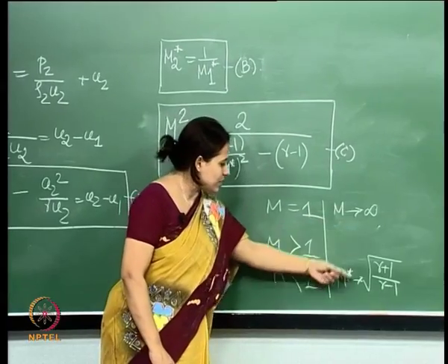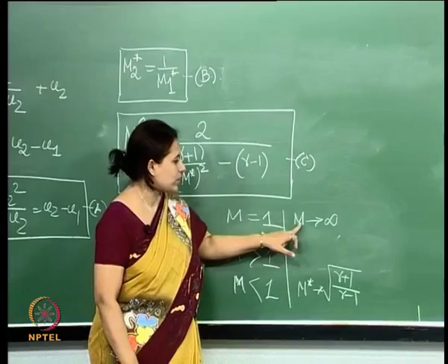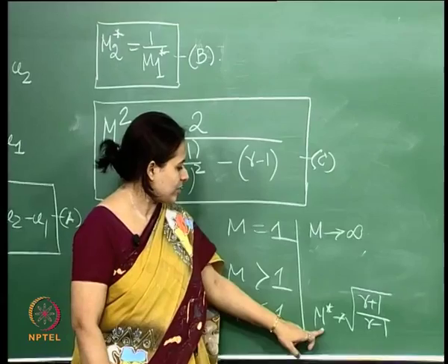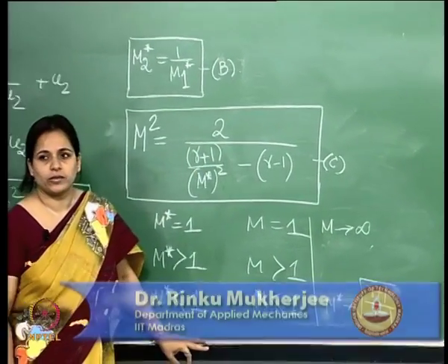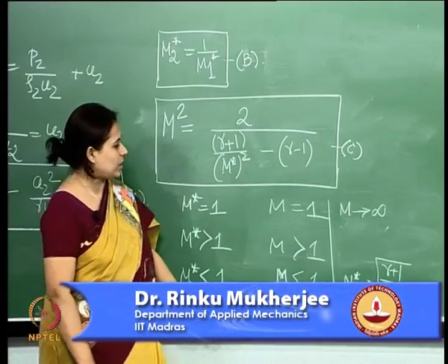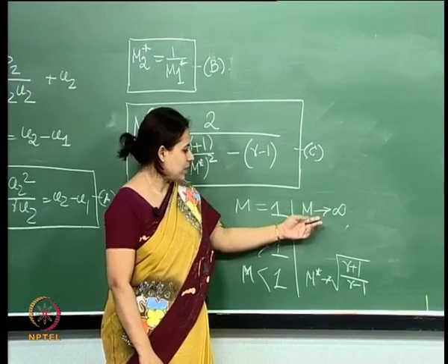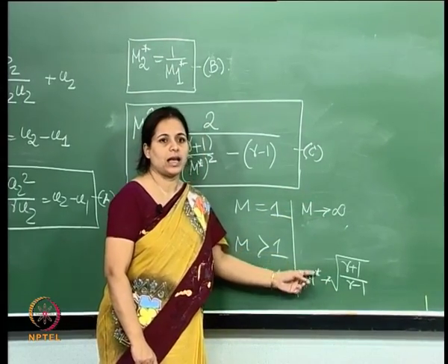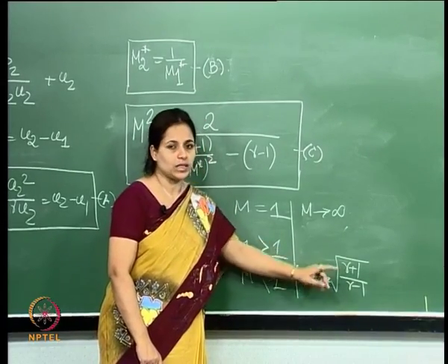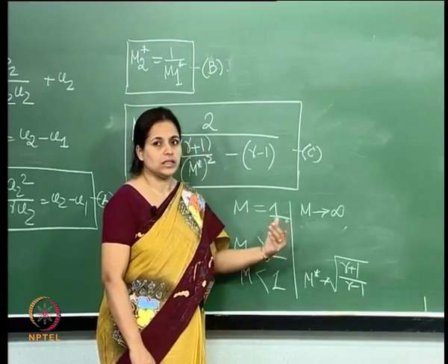Okay. So, what is this exactly telling us? The actual Mach number is tending to infinity. It is infinitely large, and then the characteristic Mach number tends to a finite value. So, if we have an exceedingly large Mach number, this m star has a finite value depending on the type of gas, because it depends on gamma, right. It is not tending to infinity, or becoming exceedingly small.